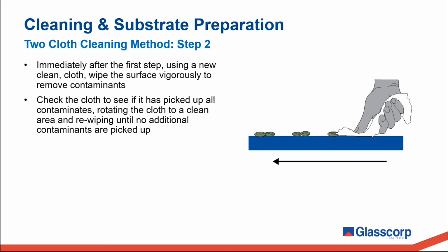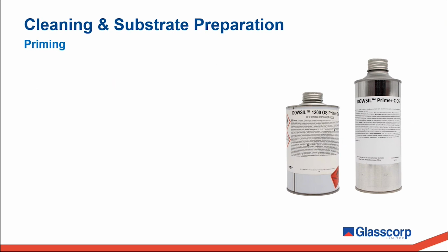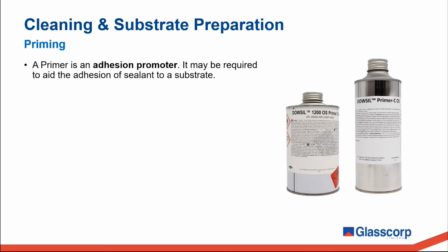Ensure that the solvent is removed with the dry cloth before it evaporates, or the cleaning won't be as effective. Now that we have a nice clean surface, the next point to consider is priming. A primer is an adhesion promoter. There are some fundamental guidelines when it comes to using primers.